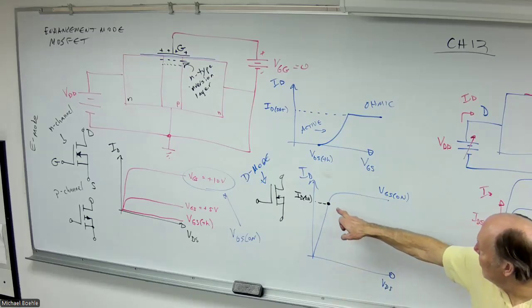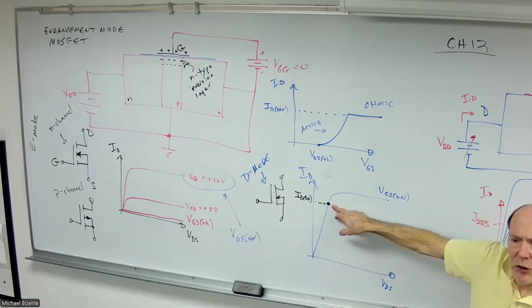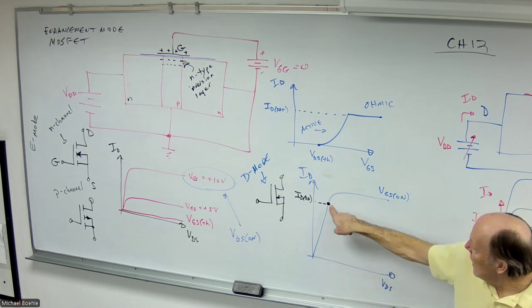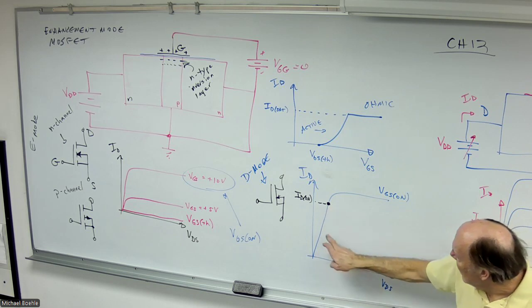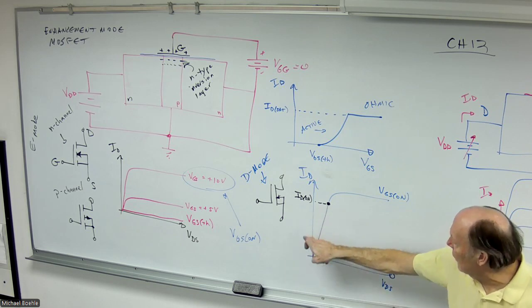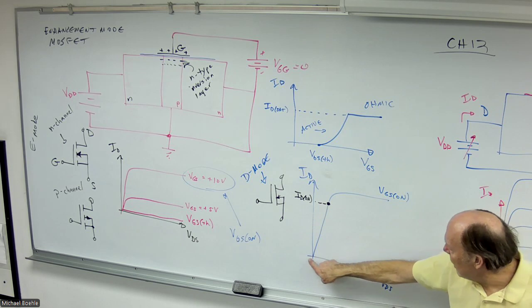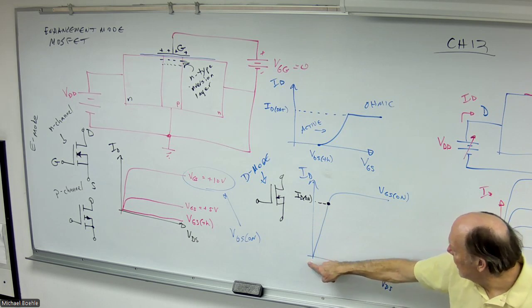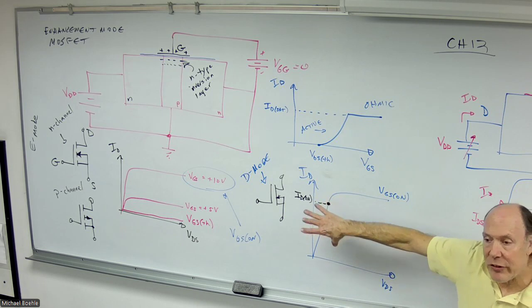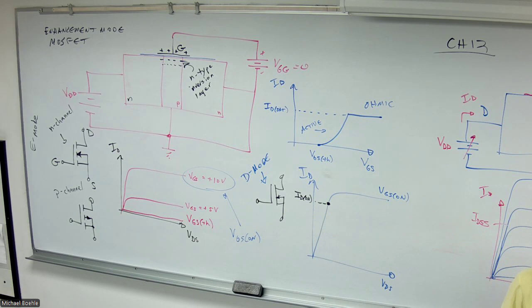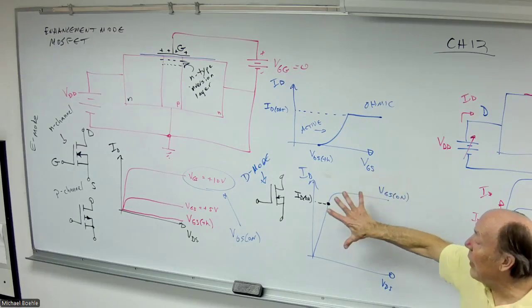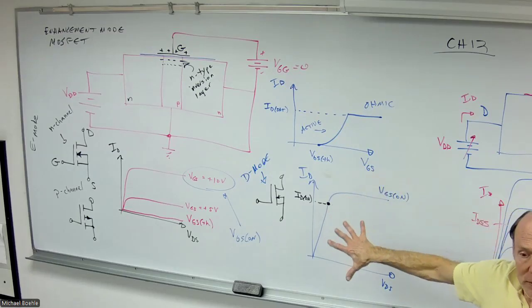Now notice where that point is, right? This is where we're kind of testing a transistor and saying, hey, as long as the drain current is below that value, then I'm operating on this part of the curve. This is a straight line originating from 0 and coming up to there. This is the characteristic curve of a transistor. Period. So as long as that's the case, then we know that this transistor will be in the ohmic region.